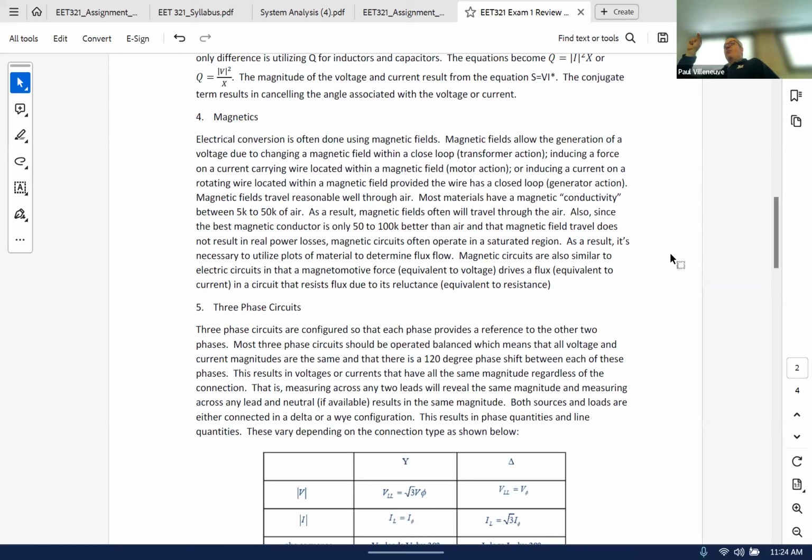When you run things at really tight tolerances, you pick an operating point, or a Q point, on your electronics, and then you assume very small changes so you can assume linear operation. So that's why you set up a Q point, and then you only run a few milliamps away from your Q point, and then you can assume linear operation. If you assume operation of the entire device, it's nonlinear and the work becomes a lot harder. Then you've got to go look at plots.